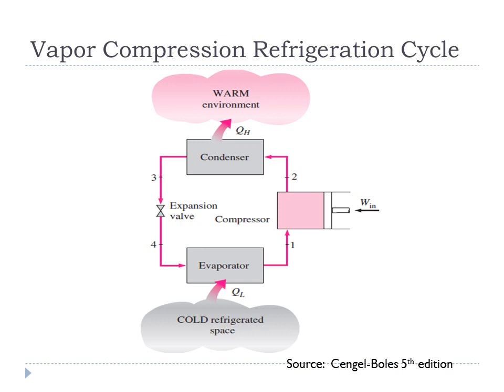So here the very low temperature liquid refrigerant which is flowing inside the tubes of the evaporator will absorb the heat from its immediate space and will give cooling effect, and after absorbing the heat the liquid refrigerant will get transformed into vapor phase, and finally at point 1, state 1, it will be saturated vapor, and the cycle repeats.